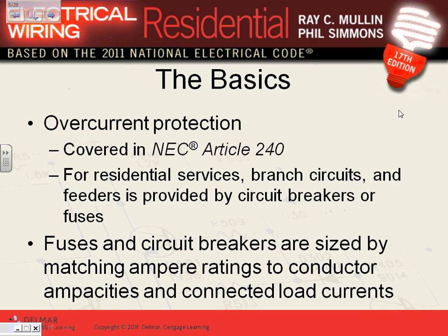Overcurrent protection device, Article 240, as you know, guys, covers it. For residential only, we will be talking about overcurrent protection devices in the commercial and industrial later. So this is just FYI, this is going to be a focus on residential. If you have a service, which you must, a branch circuit, which you must, and a feeder, which you must, these must be protected by a fuse or a circuit breaker, right?